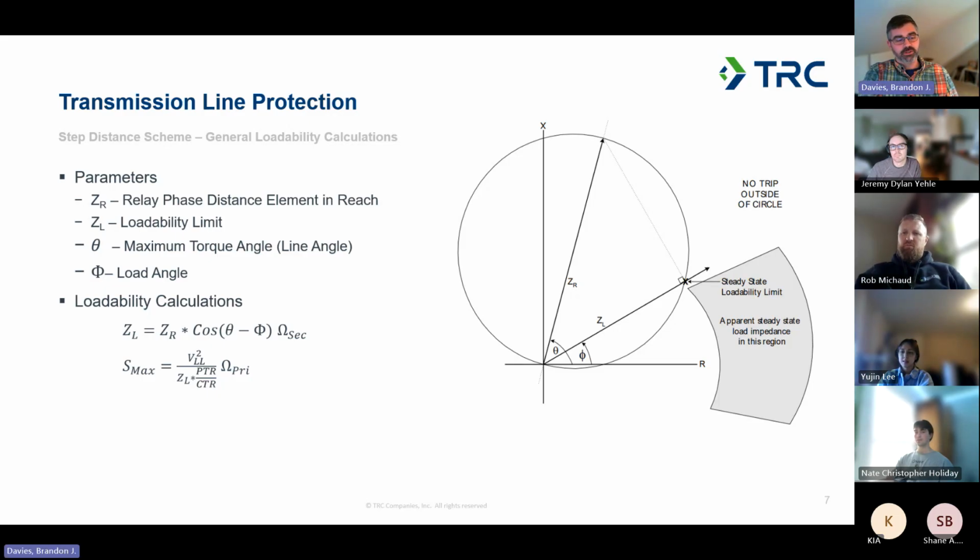It's a new concern for utilities, but it's in the interest of being able to better operate the system and maybe push it a little further than we can now by having better information. Rather than just saying winter or summer and picking one of those ratings, we're able to say, okay, this is the rating today, or in the forecast of the next several days, this is what the ratings look like.